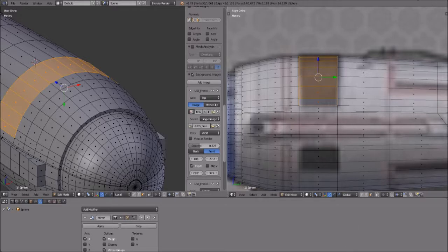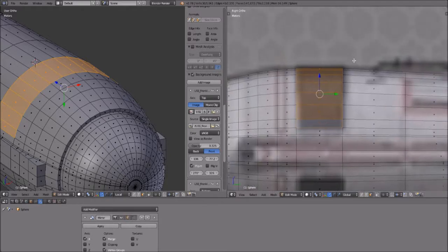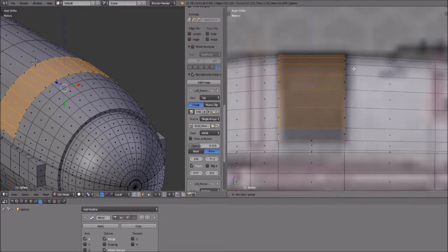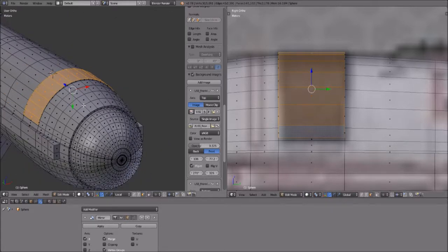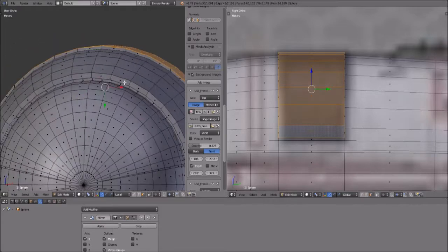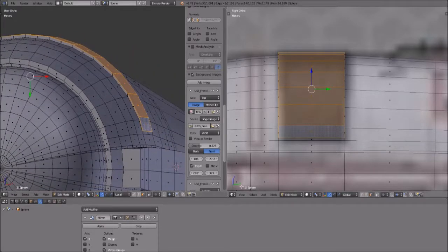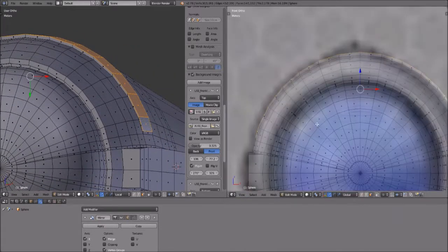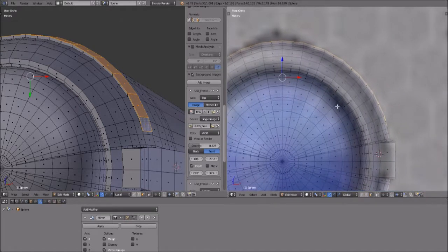Okay, no. I thought originally it might extrude in, but actually this will extrude out a bit. So let's press E to extrude, and let's try 0.15. Okay, 0.15 seems like that would work out. Now that should have extruded it in all directions. No, it didn't. So let's do a scale Z 0.1.